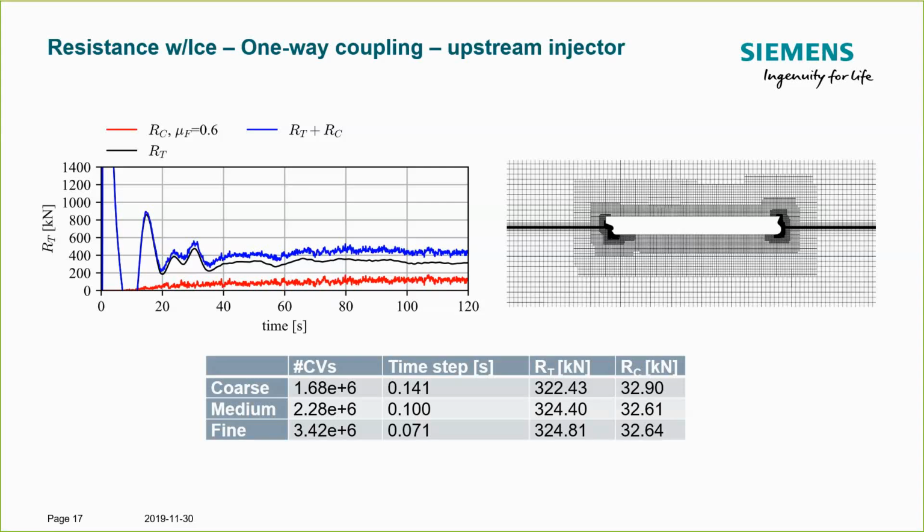So if you have a finer discretization on the hull, you will change the contact surface between a given particle size and the hull. But here you can see that apparently our initial discretization of the hull was fairly accurate in terms of the shape, and the changes in contact resistance were negligible between all three discretization levels. So in the remainder, we will work with a medium grid to economize on computational cost.